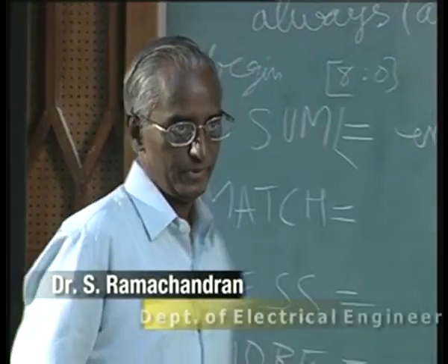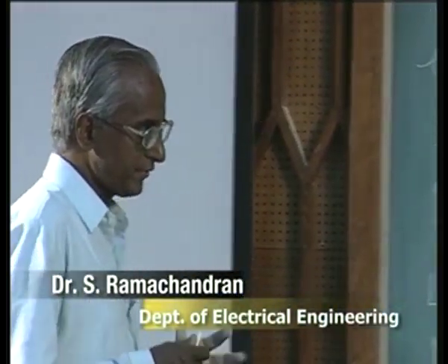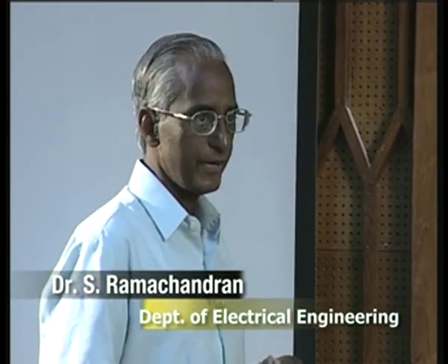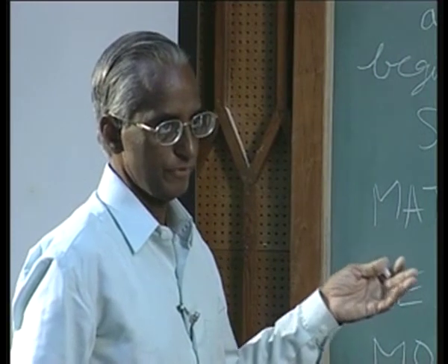That's all the difference. And to summarize the whole thing, we have covered simple gates, where the symbol is ampersand for AND, a vertical stroke for OR, and a cap for exclusive OR, and so on. And then we have seen how to use assign and always blocks in order to achieve any combinational circuits. In this way you can make any complicated combinational circuits as such.